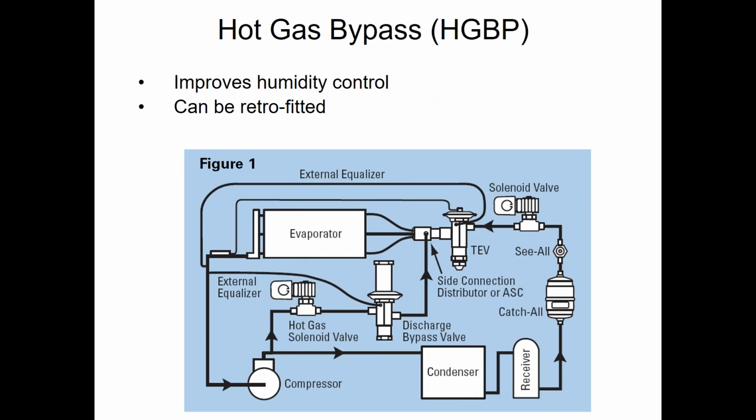You can do what's called hot gas bypass. Now, this is not an official stage of compression, even though it's kind of like having a cheater stage. And as far as the energy code is concerned, which we'll talk about later on, it does not count as a stage of compression, but you may still want to do it. So you may have a system that's kind of small in tonnage and you can't get 6 compressors or whatever. It only comes in a 3 compressor version. You may want hot gas bypass on the lead compressor of a 3 compressor machine. So it kind of gets me a 4th stage.